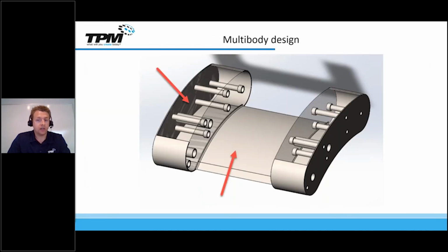So of course, we've decided that we're going to move forward with printing the component, but we want to add a little bit of stiffness to the component so that it can't warp during the printing process. After all, that 2mm wall thickness we prescribed is quite thin, even though it meets our design criteria for the minimum for the factor of safety.